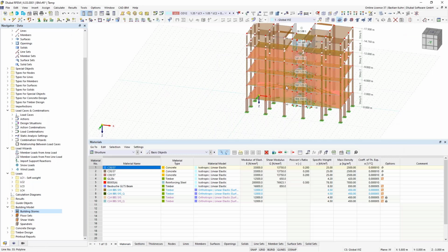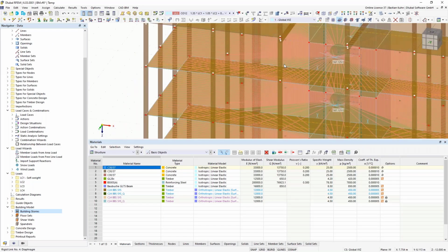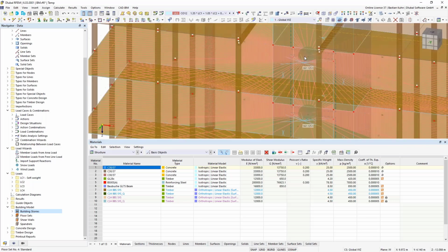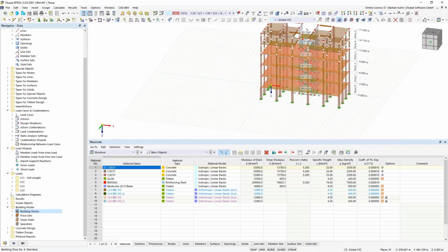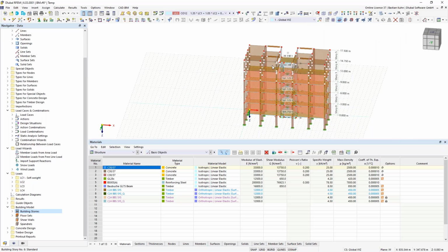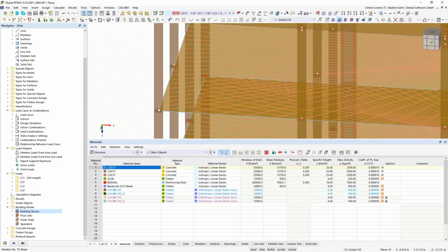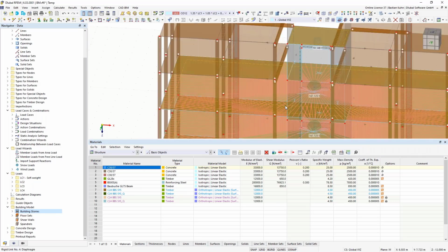And now you see here a lot of red lines, I would say. These are rigid couplings which go from, and you see a blue bubble in here. The lightest one is on the top story, 28.59 something tons. And then, okay, concrete is the heavier material. It goes up the further down you go. And these red lines, or these rigid couplings, are centered in this mass center, and they are connected to each of the columns or each FE element in each story.